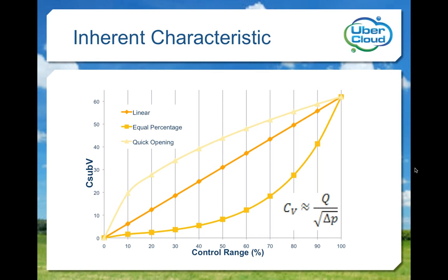The relationship between restriction and control position describes the valve's range of control. The system designer selects a characteristic for the valve based on the projected requirements. The designer can then input the applicable valve ratings in the control algorithm to permit rapid, overdamped response in order to maintain system stability during input parameter changes and other disturbances.